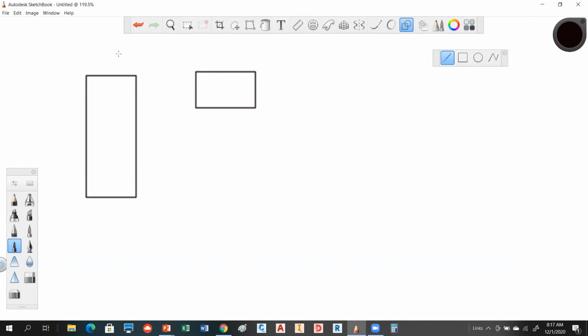Let me put a centroid. This would be the line of the centroid coming down through like this. But we have a force that's coming down over here. So it's off-centered. It's definitely what you would call eccentric. It's loaded right here, and this is 15 kilonewtons. This distance here of eccentricity is 100 millimeters. So we've got a unit issue we're going to be dealing with as well.